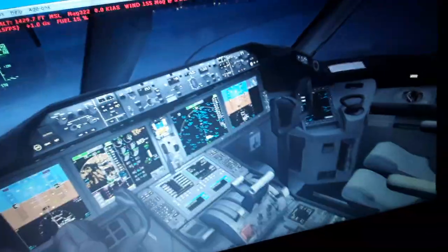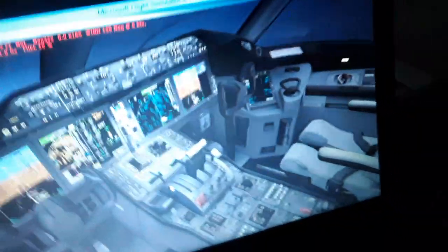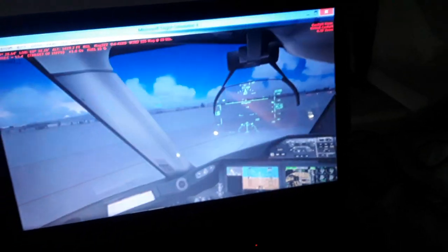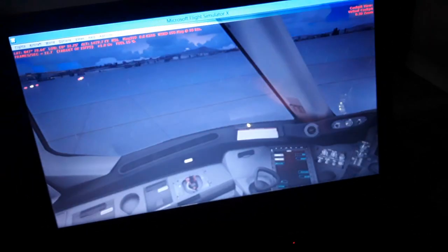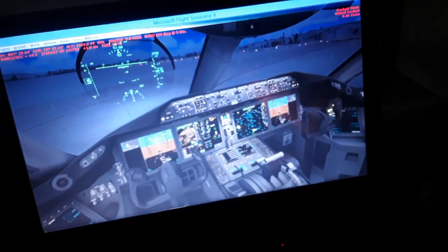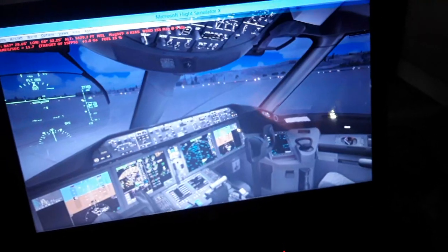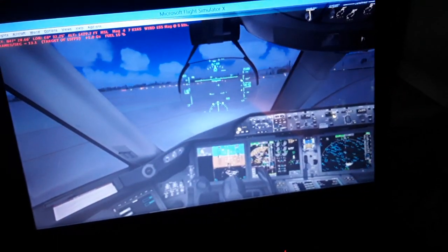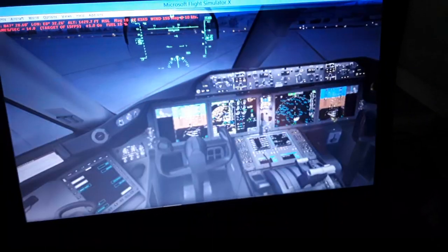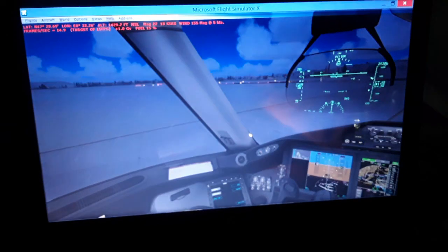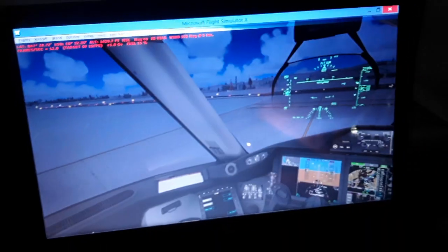So we use flaps now for takeoff. With brakes retracted, parking brakes off, and we go in for takeoff. We take the runway clearance. Advance the thrust levers here. So idle thrust for alignment. The taxiway, the runway is open for us. For takeoff, we take the runway clearance.